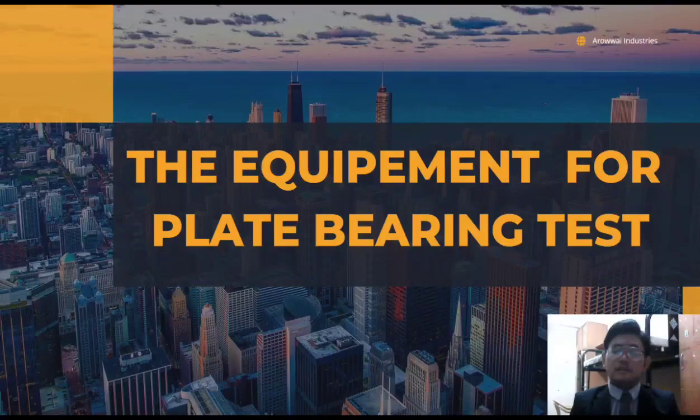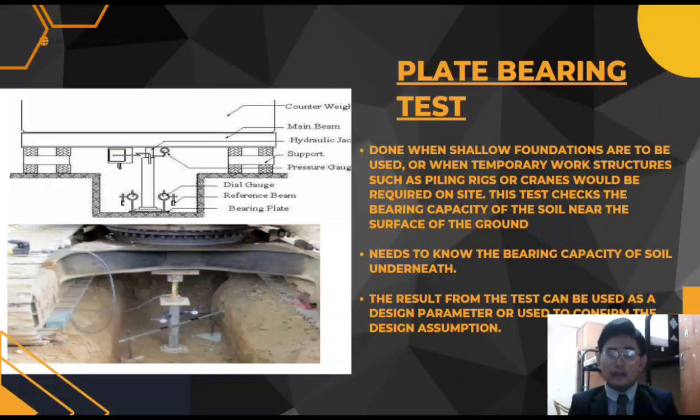As you know, the plate bearing test is done when shallow foundations are to be used or when temporary work structures such as piling rigs or cranes will be required on the site. This test checks the bearing capacity of the soil near the surface of the ground. We need to know the bearing capacity of the soil underneath because the result from the test can be used as the design parameter or used to confirm the design assumption.